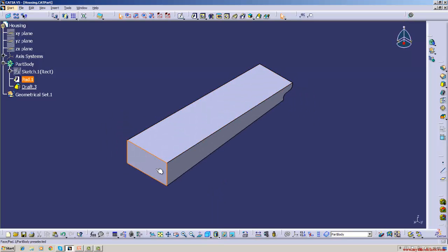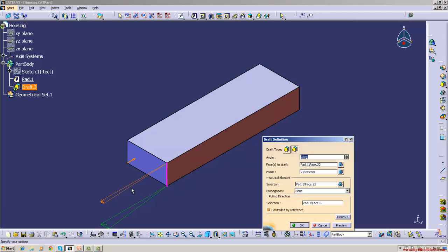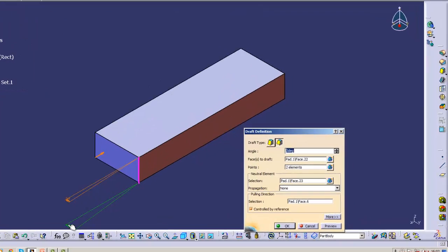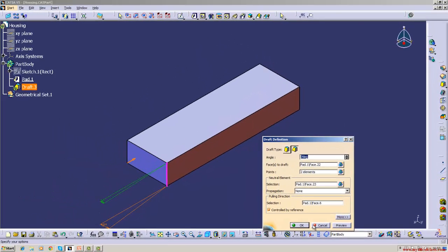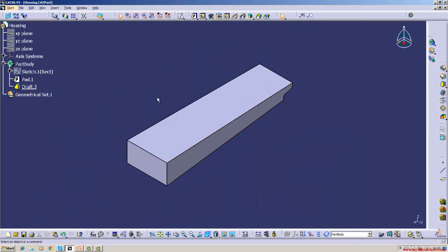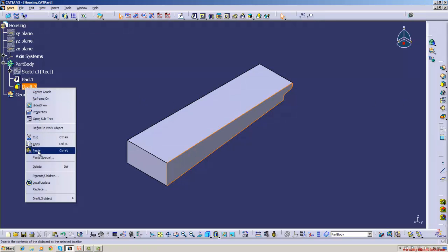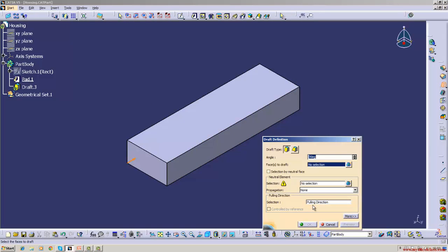So with respect to this face, this edge will have some other angle. Say with respect to this face, the inclination is 1 degree or 3 degrees, and this will have 7 degrees. So this inclines like this, tapering to 7 degree like this. This proceeds at 3 degree like this. At this end, it will be twisted. So this is how we can give different angles. Let us know about these things, and I will draw once again.